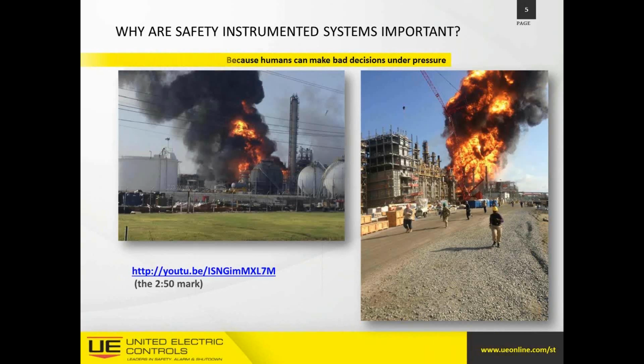The difference between the two is significant, but yet sometimes not difficult to separate. A basic process control system continuously operates the process in the plant during normal startup, running, and shutdown phases. But the safety instrumented system brings the plant to a safe state if hazards are existing.